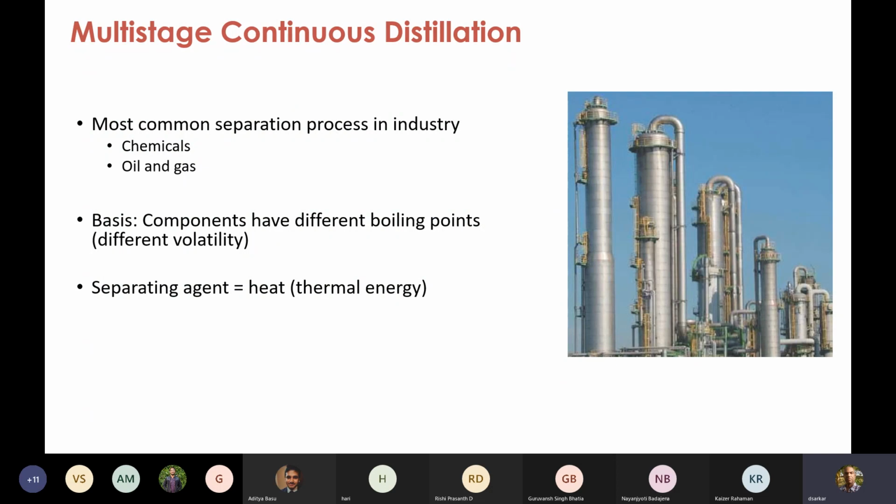So you have basically now two different liquid mixtures, and they will differ in concentration. The condensed vapor will have more volatile components in it compared to the other part. So basically you have done some kind of separation, but you can imagine that this separation will be limited.